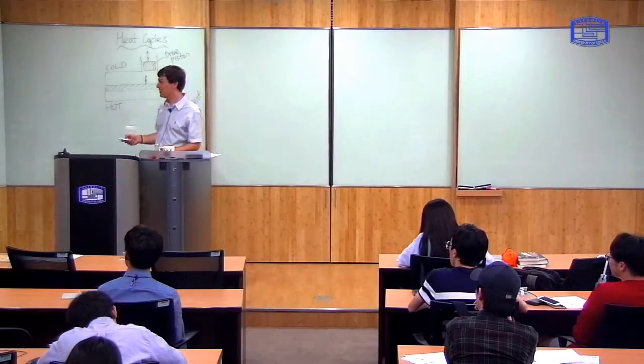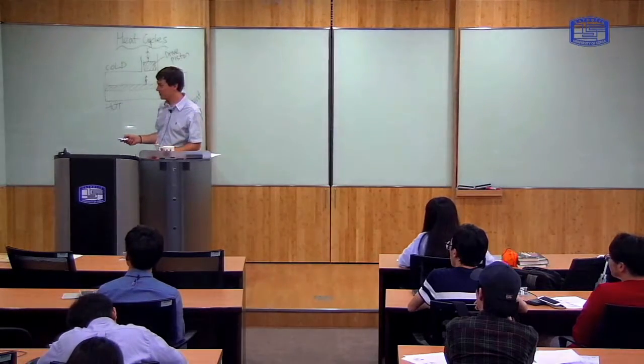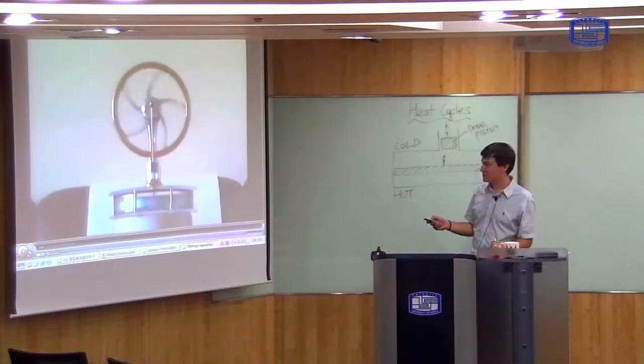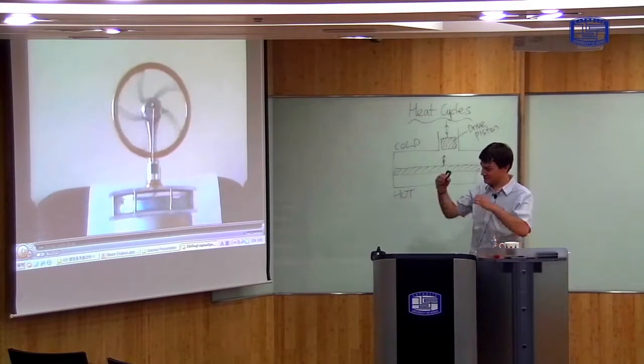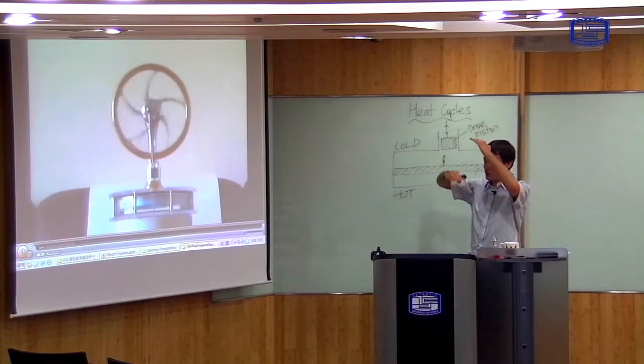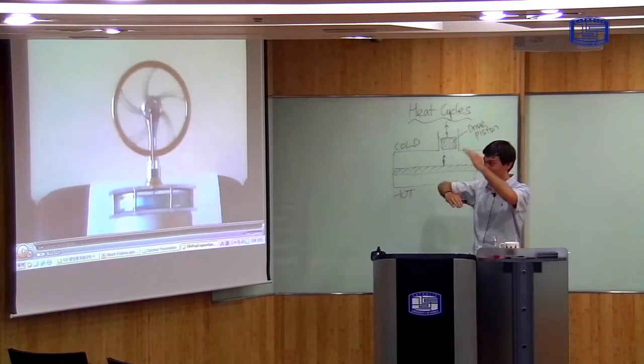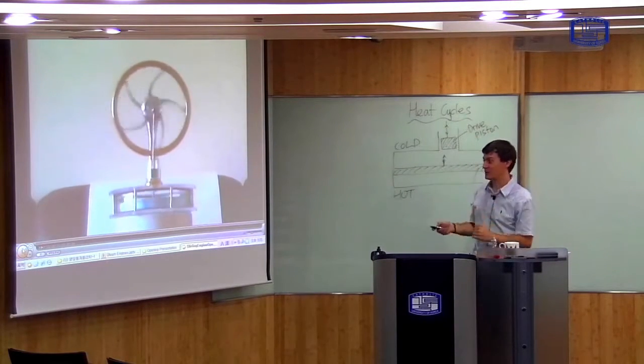that they are out of phase. The displacement piston goes up first, and then the drive piston goes up 90 degrees later, 90 degrees out of phase. Okay? So that they follow each other like this. One goes up, and the other one goes up, one goes down, the other one goes down. Okay.